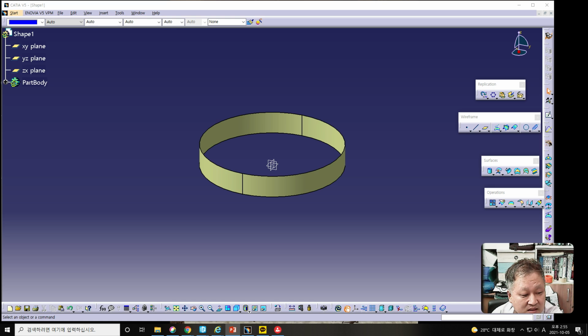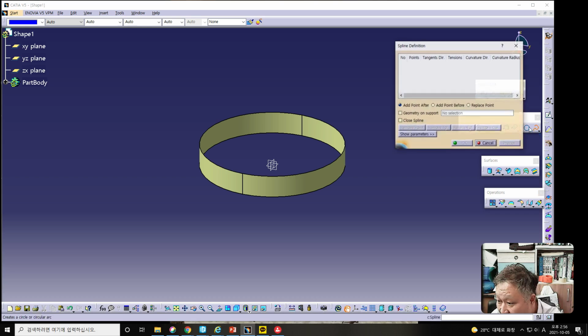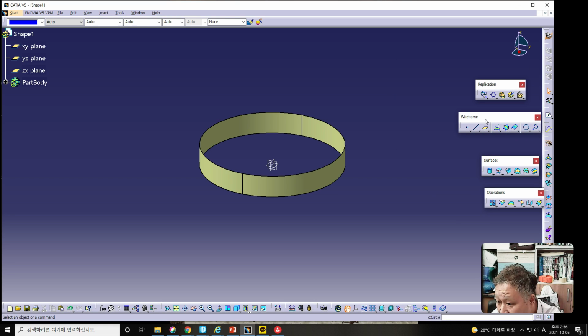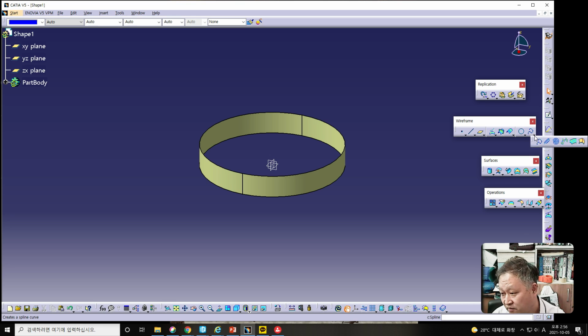If you have the cylinder set up as in the picture above, then at this time please click Helix. The Helix button is placed in the wireframe and surface toolbar, the first one, then counting 1 2 3 4 5 6 7 8th one.